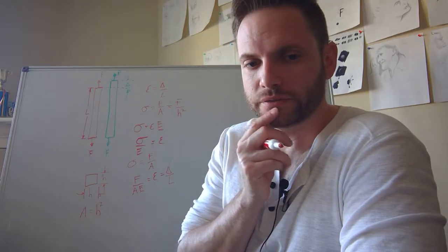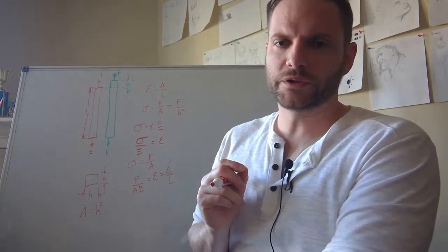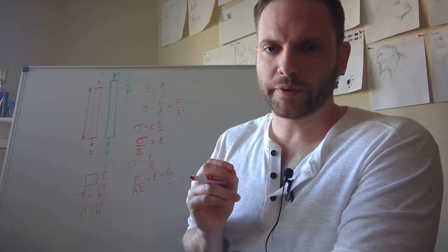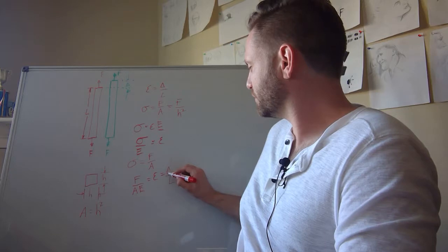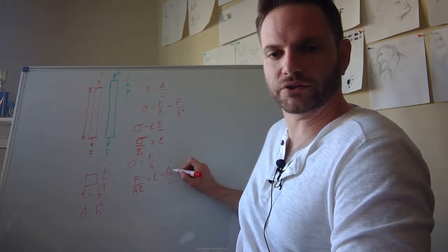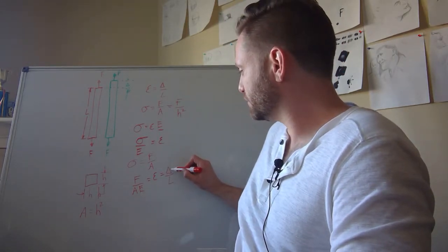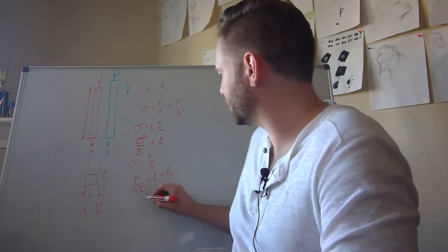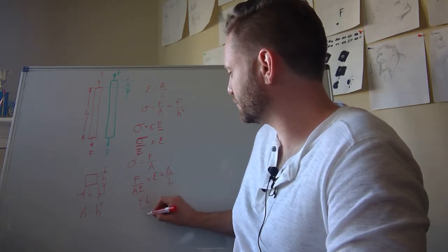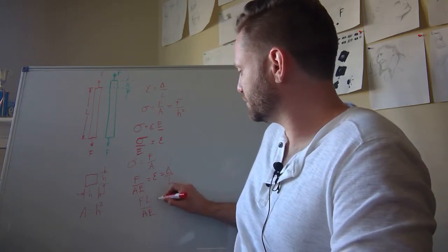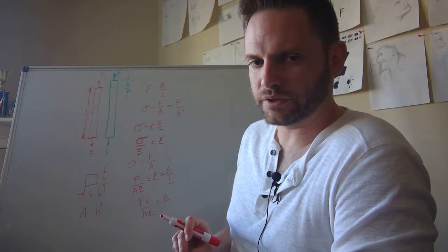That's interesting a bit. Because before we were talking about, in a previous video, the spring constant of things. So we look at this, we have this length delta. This is what's actually going to change. This is the displacement that a bar or some kind of object experiences. So I can rewrite this equation one more time, so that force times L, which is the original length, over area times the modulus is equal to delta. It's getting a little bit closer to where I want it to be.